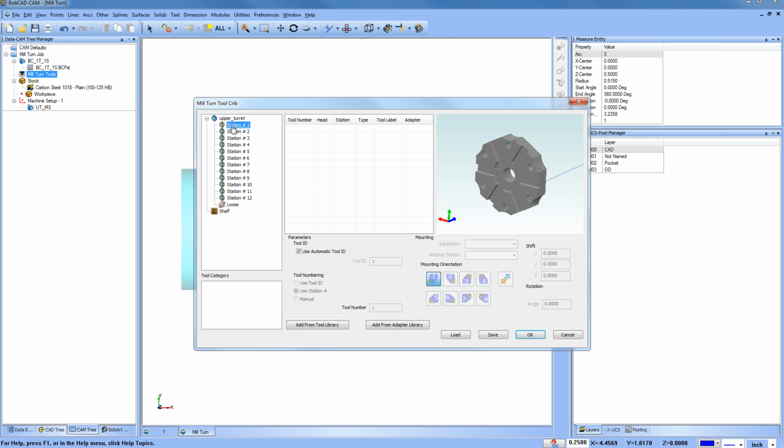The stations are what's going on at those stations. Loose is when you've called the tool through the machining wizard, like a profile or whatever it is that you're doing when you're generating toolpath, but that tool isn't mounted. That is what a loose tool would be. A shelf tool would be when you unmount a tool that isn't being used in the job, it goes on the shelf.